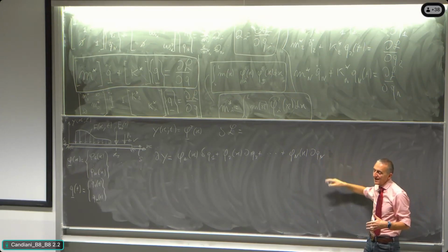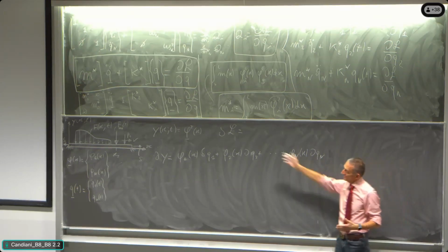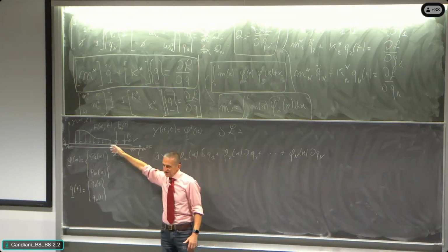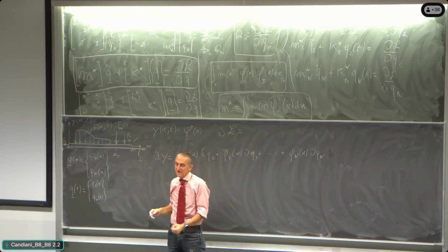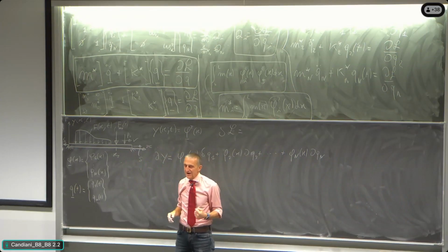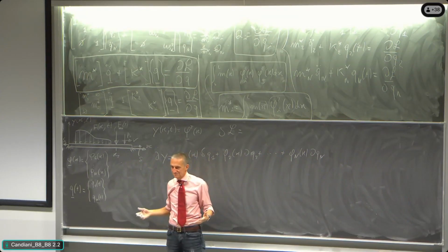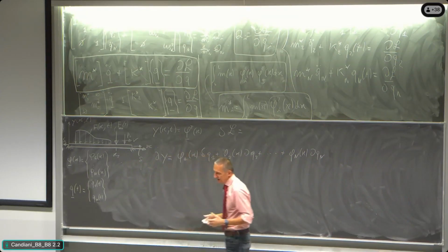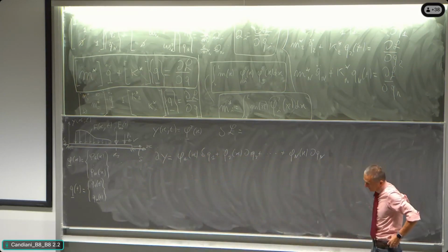The modes that are actually activated, typically, by the excitation. The modes that are activated by the excitations are the modes that have the frequency within the spectrum of the excitation of the force, typically, all right? And so we have a clear idea of what is needed in order to give a good representation, typically.